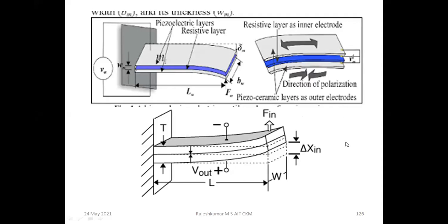That input force will affect the cantilever position, which is considered with regard to the thickness T. If the thickness T gets thicker, then a maximum amount of force can be applied, but the input voltage also has to be increased. So that's why, regarding the working conditions, they are going to decide whether we have to go for a minute thickness or a huge thickness. The length and width will be with respect to the application.